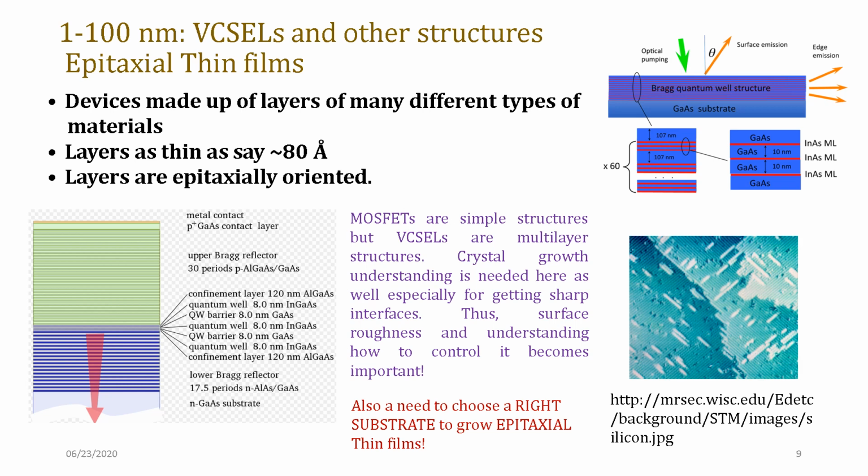And what is this going to give? It's going to give us an enhanced property. This cavity is going to give a lasing action, which means with gallium arsenide as a substrate, and then a stack of this kind of dimensions with indium arsenide, when it is stacked, you can actually see an edge emission. That means from the edges you can see light coming out.